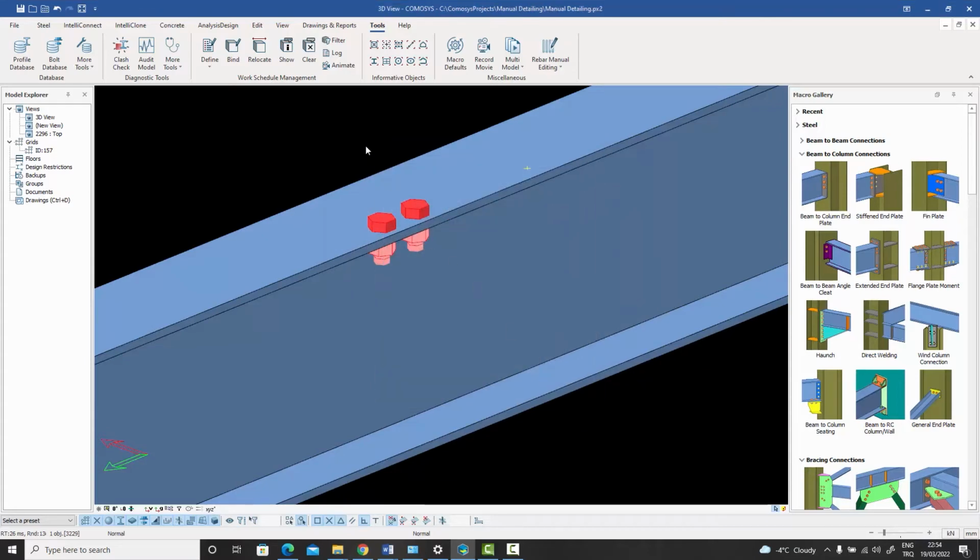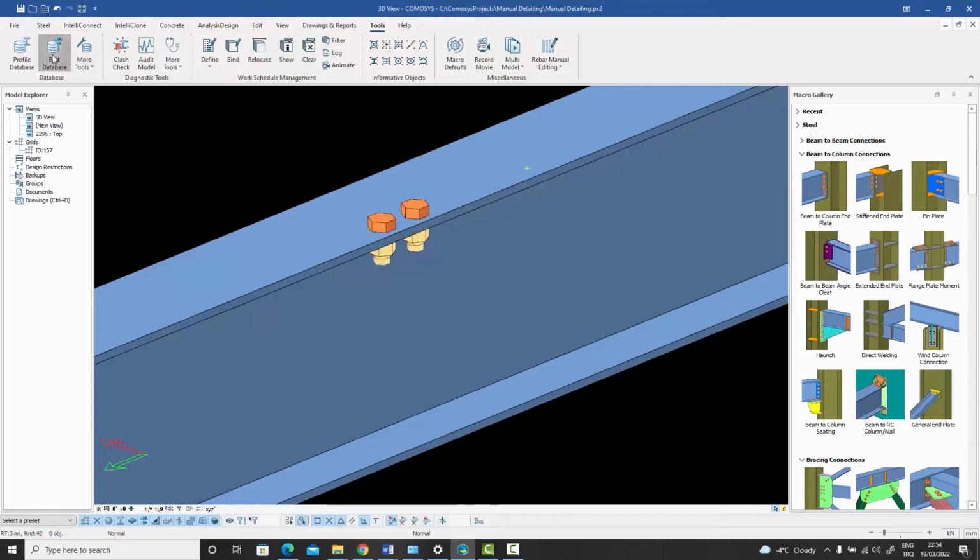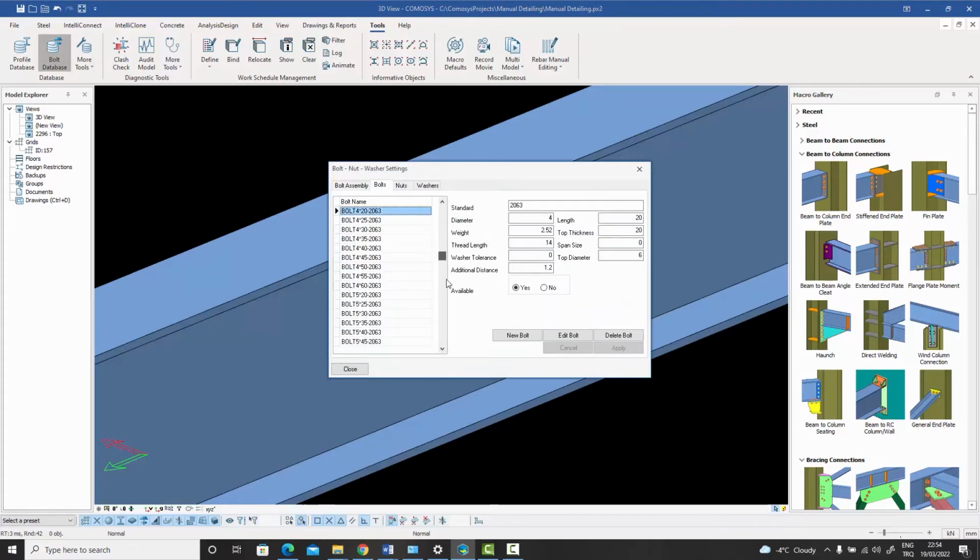Now, let's check the diameter, which is 20. If you go to the bolt database and scroll down to 6914, we get to 6914 over here. Let's go to the M20 bolts. Let's scroll a bit further up. Now you see over here that the M20 bolts have a maximum. So this is the last M20 bolt, or let me see. Yes, this is also M20. This one is the last M20 bolt, and the length is 155 millimeters.